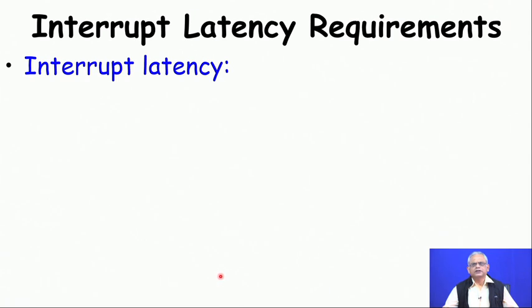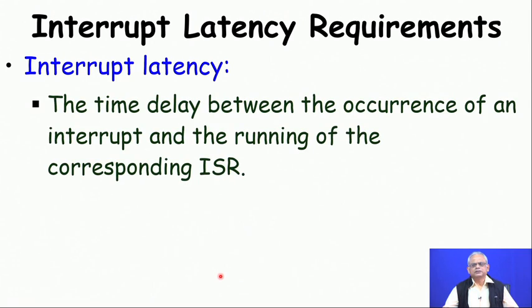There are also interrupt latency requirements on a real time operating system. What we mean by the interrupt latency is that when an interrupt occurs, the time by which the interrupt service routine runs for that interrupt must be small and bounded.